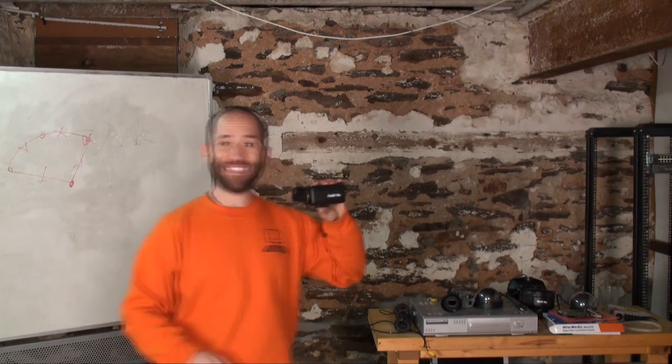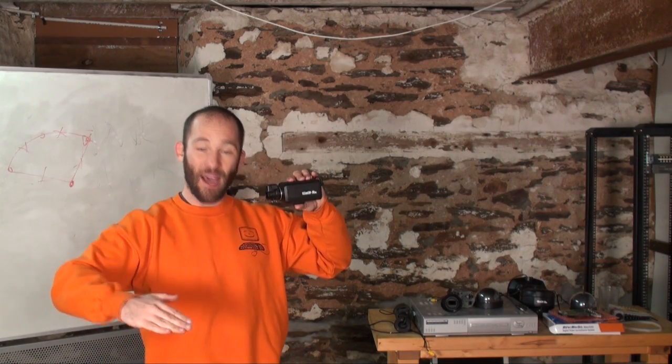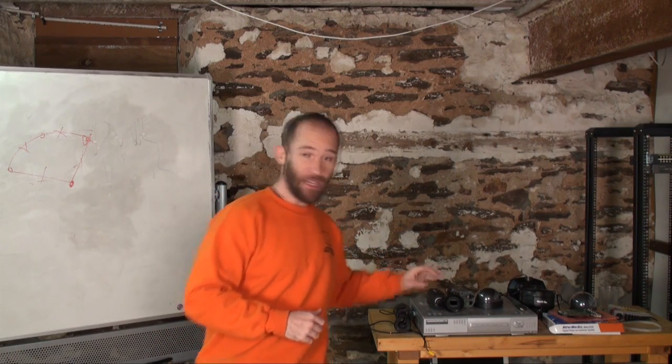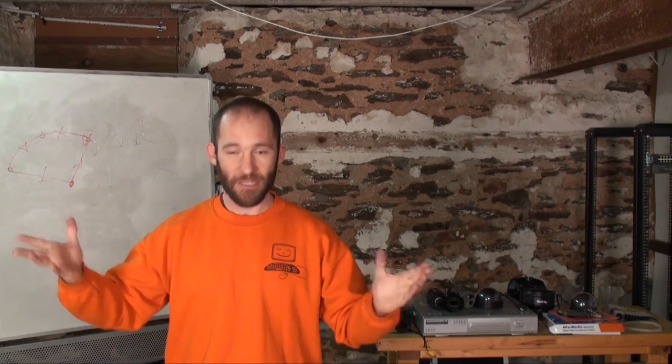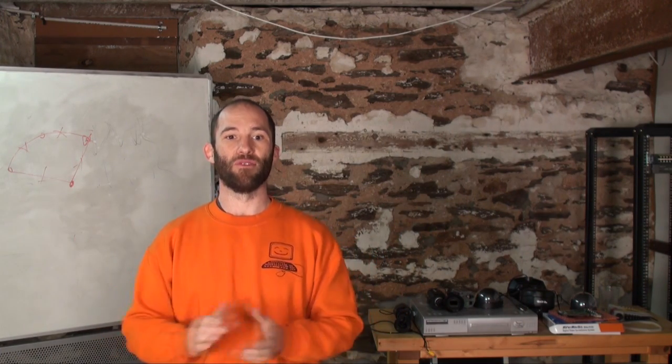We talked about resolution. With analog cameras, we're talking about TVL, TV lines, the horizontal lines on an old-fashioned CRT, cathode ray tube TV. 600 TVL is DVD quality. Again, not as good as you think it is. 320 TVL is very low quality. You can see an orange blob move across the room. With IP cameras, you're just dealing with normal resolution like you deal with on a monitor. It'll tell you, like 648 by 720, 1900 by 2300, whatever the resolution is.